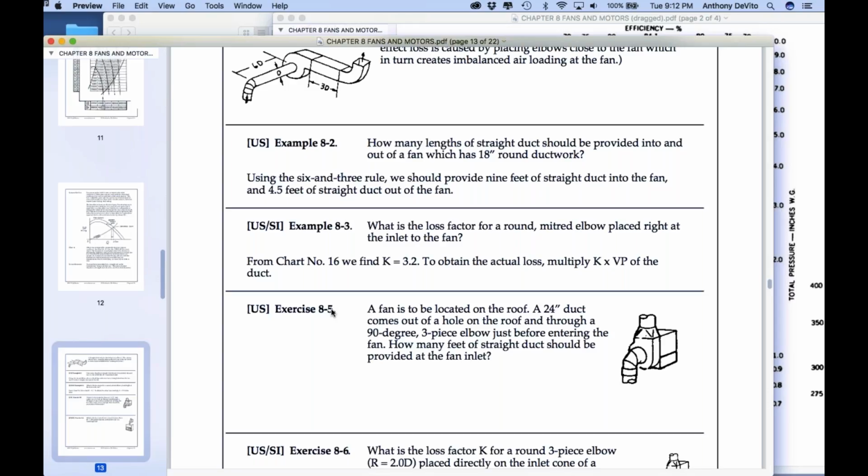The only problem with that is that when they're abating asbestos, they're in the middle of that stuff. That's why they wear the respiratory protection. The ventilation they use in those systems is to keep negative pressure, so it doesn't escape the containment. They're not using any capture ventilation. I mean, as he's scraping it, he could have one of these flexed-up fan hoods go up against there, like a welder might use, and capture. But you don't see them doing that. They're scraping in the big room and containing it, but they're using PPE as their primary protection.